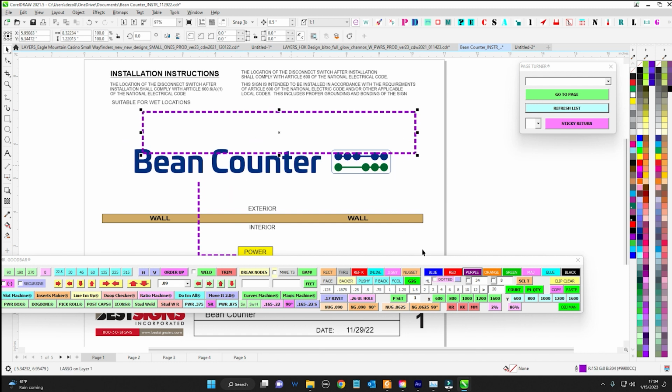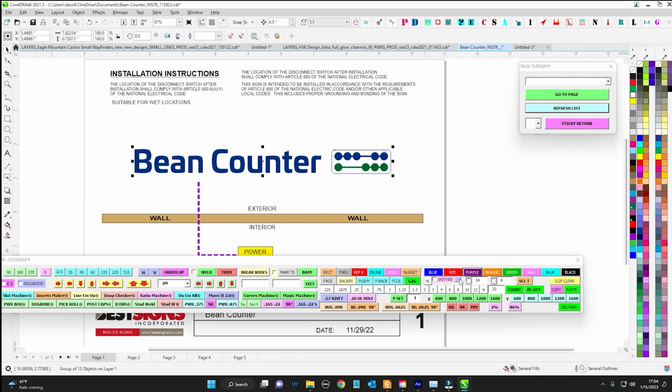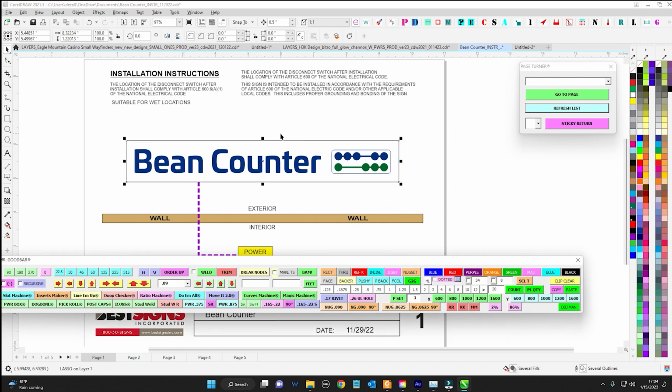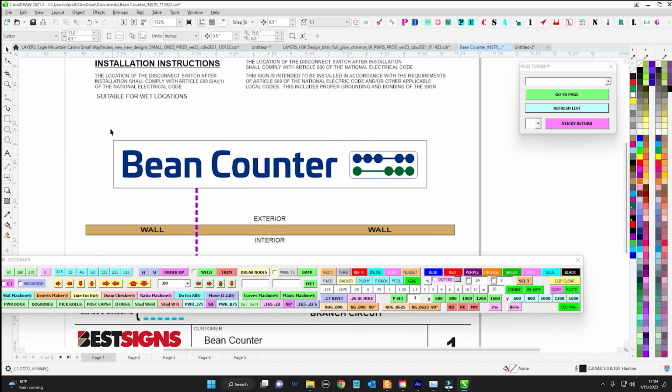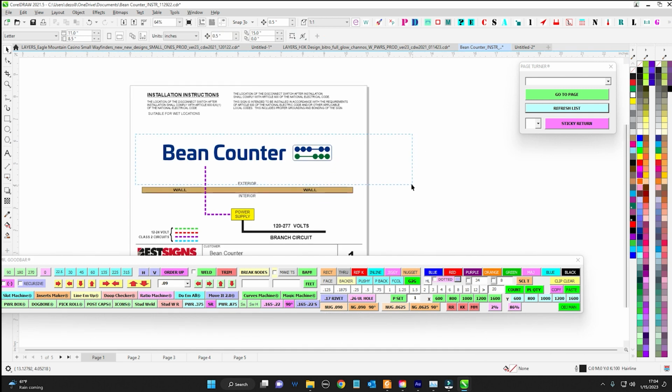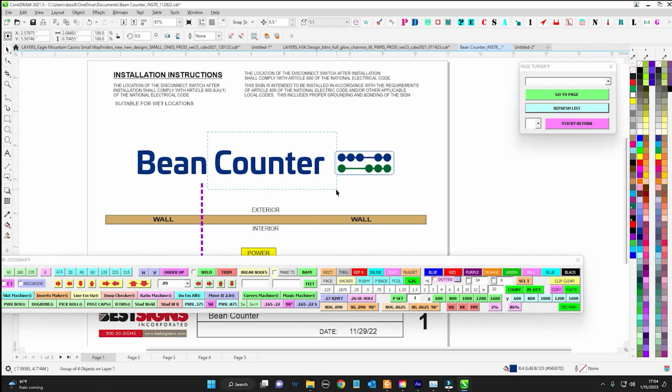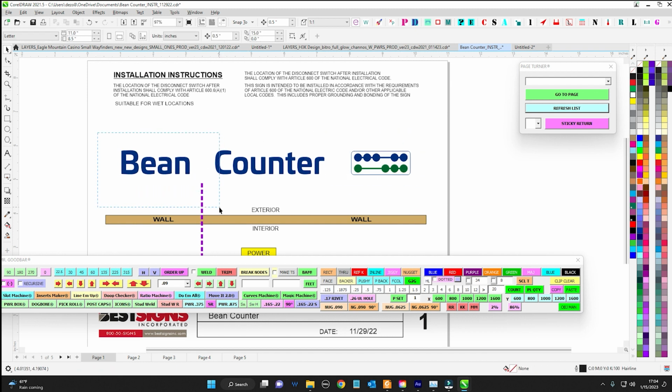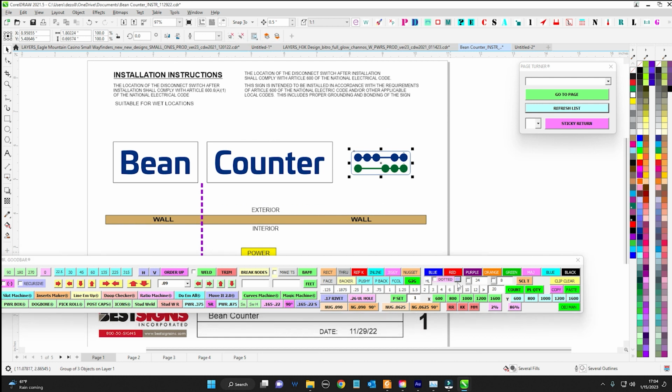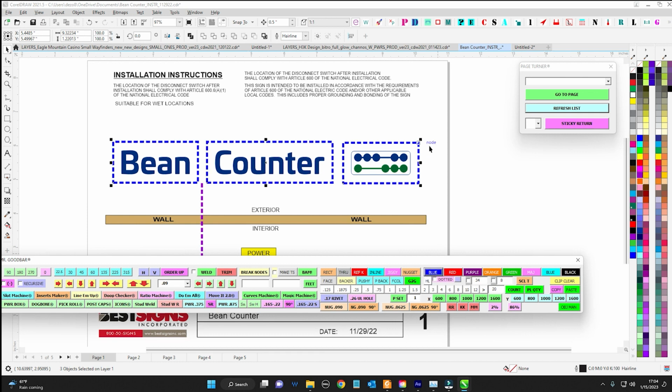If I go like this and surround this and push this button, it names it as lasso. So I've lassoed this. But you can see how easy it is if I need to do multiple circuits. If I hit group, and I group this and I group this, I can change the spacing a little bit because it doesn't matter what it looks like. Then I can just lasso each of these, and just that easily change these over to a dotted line.